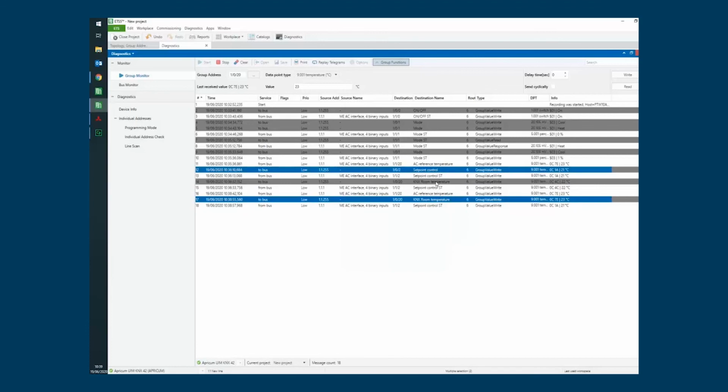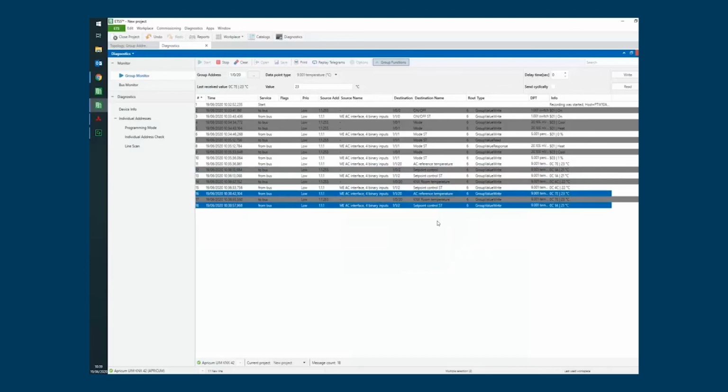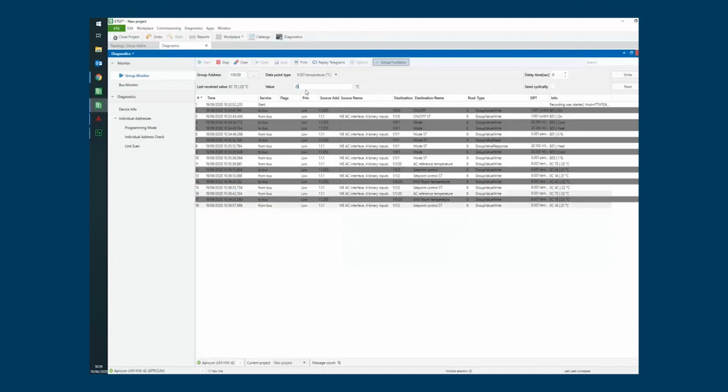And we have these 2 degrees between the return path of the AC unit and the real set point. Okay, so in the ideal case, both temperatures are coincident. Basically, whenever there is any update in this temperature, the interface will recalculate the appropriate temperature for the AC unit.